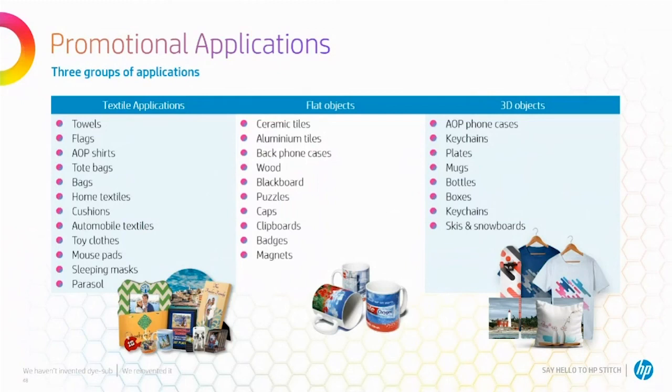But for now, our printer has a fixed dot size. So those dots are going to be more prevalent when they are sublimated onto a hard good. Now, what I'm saying here is, does the color look great? Do they look vibrant on these types of materials? Yes. But in some of the colors, like in gradients or lighter colors, you may get some unwanted grain on the hard substrates.